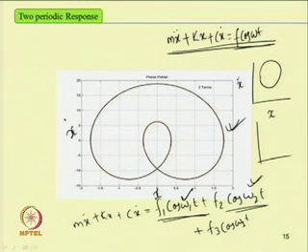we can obtain a response similar to this, which will contain three frequencies. We will have an outside loop, this is the second loop and this is the third loop. In the case of three frequencies, if you have three periods, then we will have these three. In this way, one can go on increasing the number of forcing terms, and in a linear system also one can obtain a response with a single period, two periods, or multiple periods. Similarly, in a nonlinear system, for different resonance conditions, even with single frequency excitation, one can get periodic, two periodic, or multiple periodic solutions.